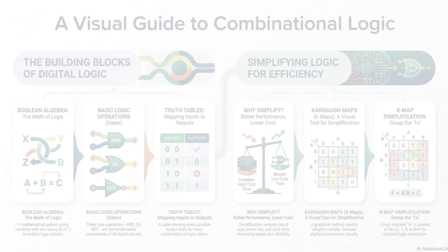Yeah. And for the exclusive NOR, the equation is Y equals AB plus the complement of A times the complement of B. Okay, so that means the output is 1 if both A and B are true, or if both A and B are false. The condition of equality. Understanding these derived functions is really where the whole optimization game begins.